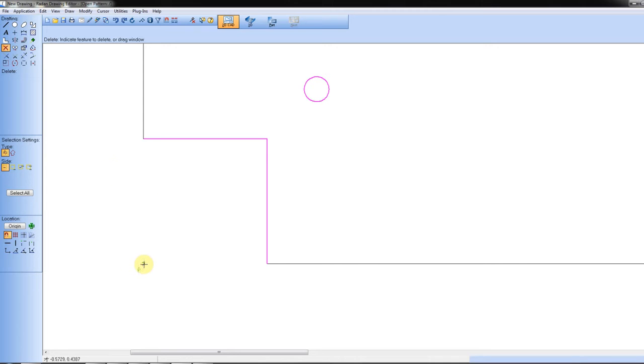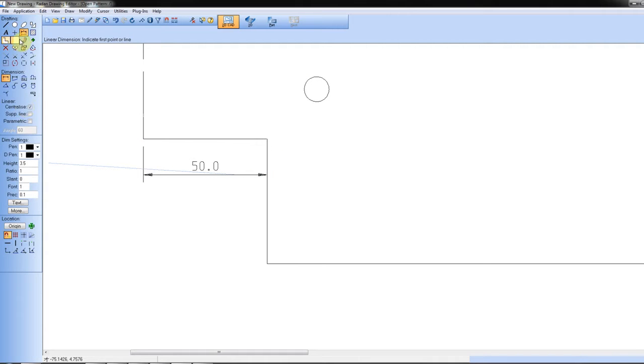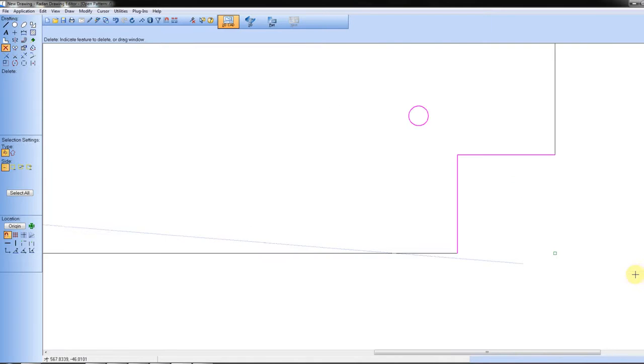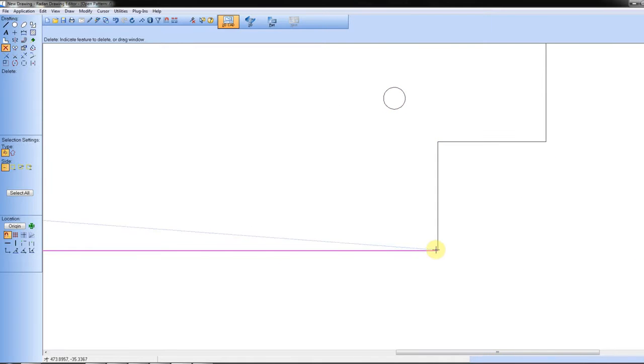Okay, we will start here by inserting a corner symbol in this position. Notice the symbol's origin. Next we want to draw the bottom line, so we need to move the pen by 50 mm in the X direction. Once that is done we will draw a line in the X direction by a length specified by the user's answer to the width question. Then we will move the pen by 50 mm in the X direction and insert the corner symbol, this time in a mirrored state.